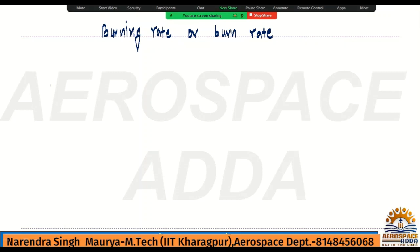Second is the combustion chamber pressure. This burning rate also depends on the combustion chamber pressure, just like in jet propulsion, the mixing and burning of fuel in the combustion chamber of the jet engine also depends on the combustion chamber pressure. That's the reason we require a compressor to increase the pressure and the temperature. The air entering the combustion chamber should have very high pressure and very high temperature. Once you inject fuel, fuel and air start burning. So there also the burning rate depends on the combustion chamber pressure, and here also the same thing.